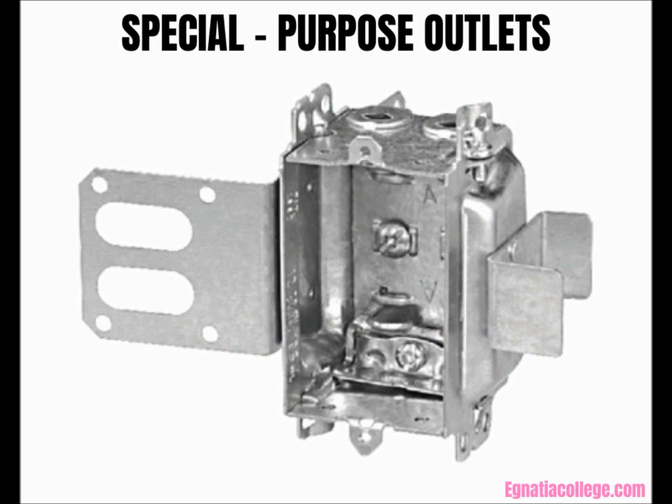When a special purpose outlet is indicated on the plans or in the specifications, the electrician must check for special requirements, such as a separate circuit, a special 240-volt circuit, a special grounding or polarized receptacle, a device box with extra support or other preparation. Special purpose outlets include central vacuum receptacle, weatherproof receptacle, dedicated receptacle, perhaps for a home computer, air conditioning receptacle, clock receptacle.